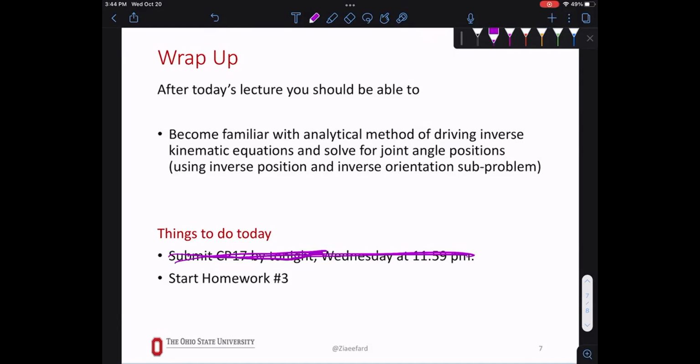Let's say you have a manipulator robot. I'm just going to use the 2R because I can't use my arm. So this is a 2R, with one link going here, one going here. Let's say this manipulator is manipulating something, and it hits a wall or touches something, so it has to push. When it contacts an object, or a wall, there will be some force and moment generated at the manipulator. If it's touching the wall, it's going to be a contact force.